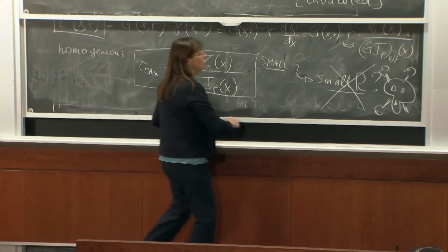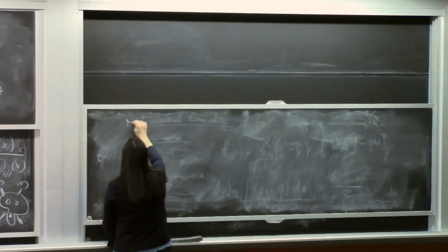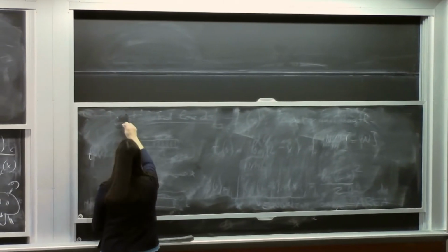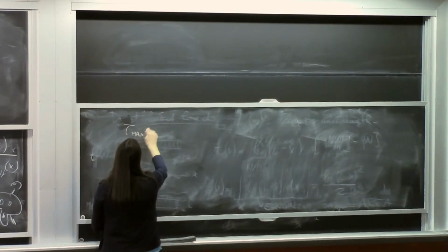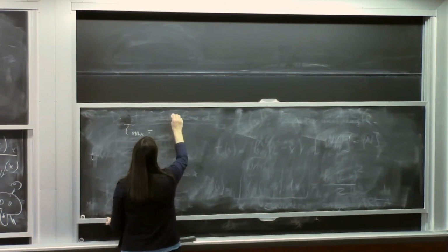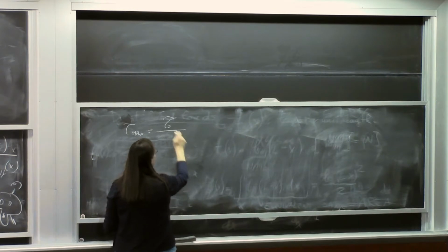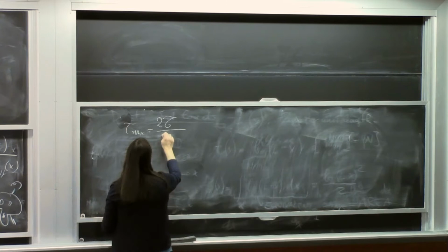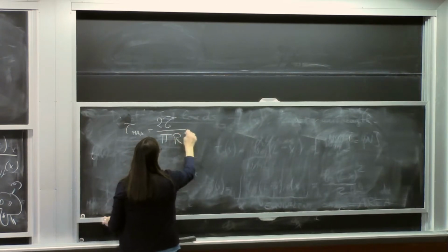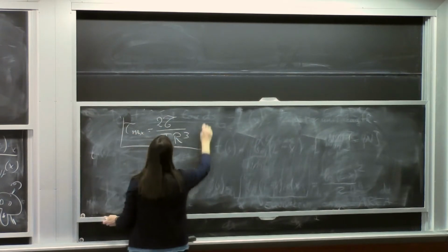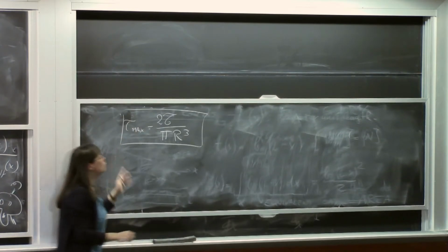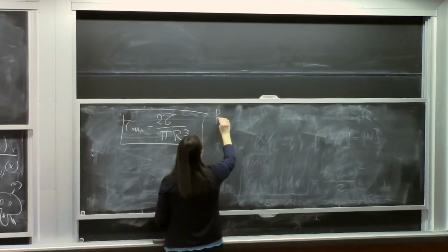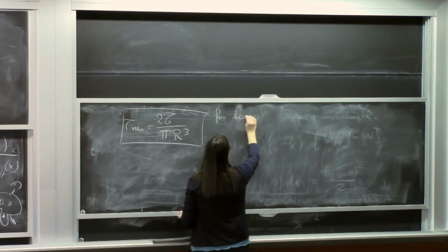So if you substitute the value of IP, you find that tau max is equal to the torque divided by pi r to the fourth over 2, so there is a 2 on top, and one r to the fourth cancels with that, so you get pi r cubed. Right? So this one is the maximum stress for a homogeneous shaft.